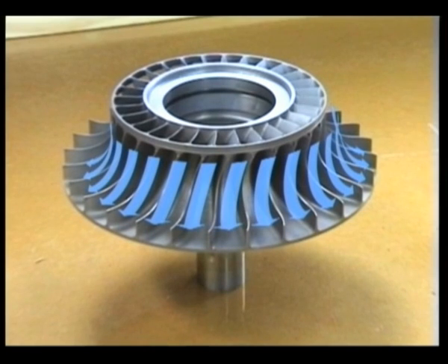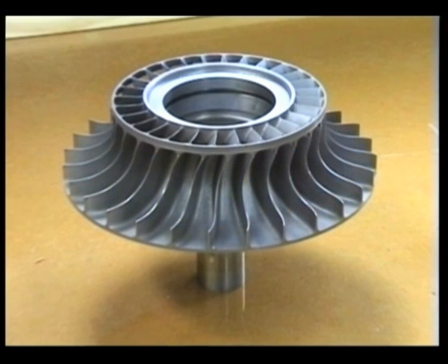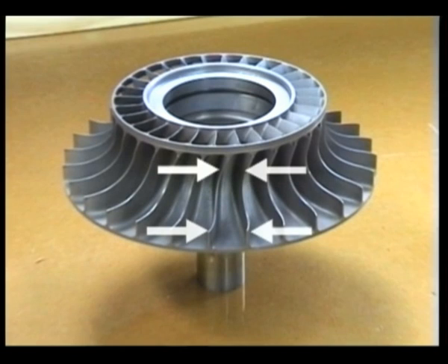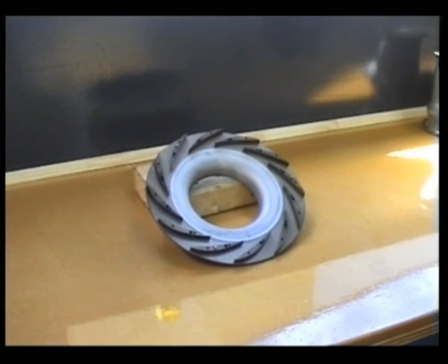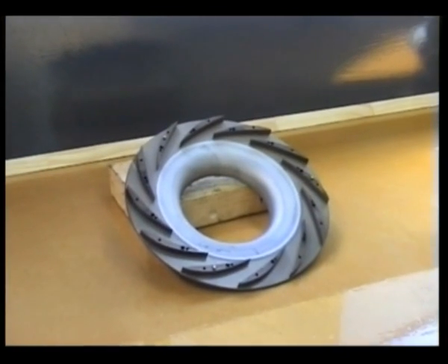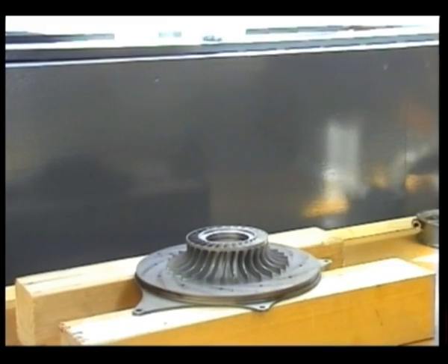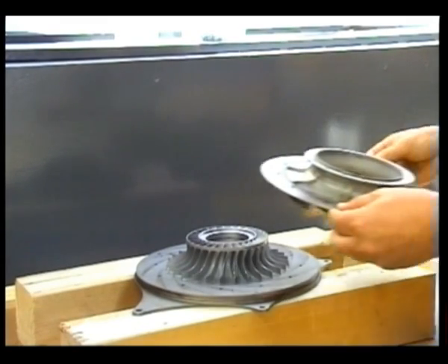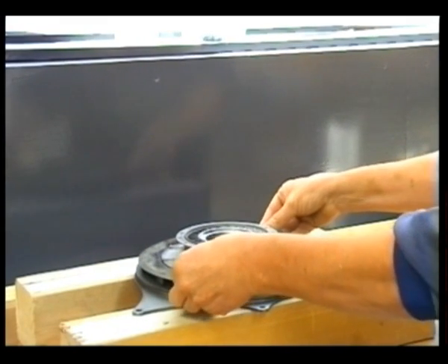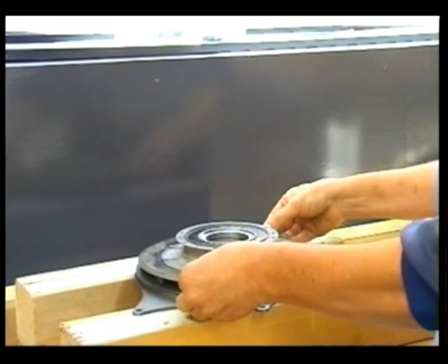Pressure of the outflow air rises because of the diverging passages between the vanes. The air then passes through a diffuser where the velocity energy is converted into pressure energy. Velocity is reduced and the pressure increased. A rise in temperature results because the work carried out by the compressor in compressing air involves adiabatic heating.